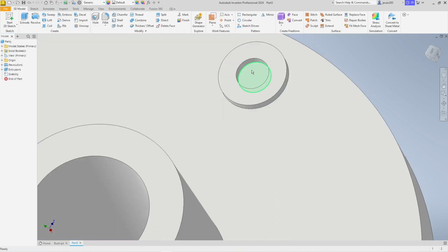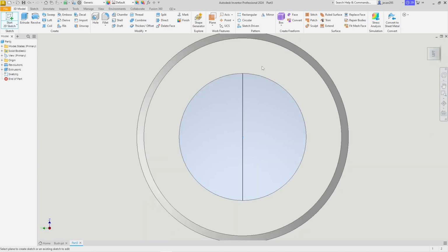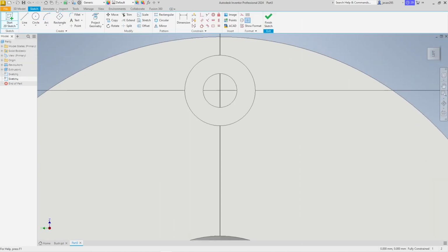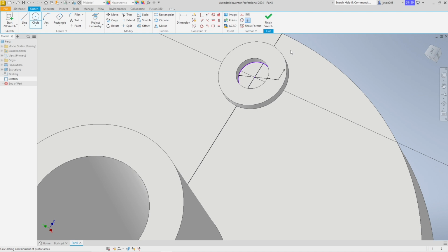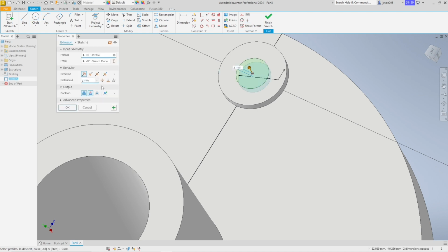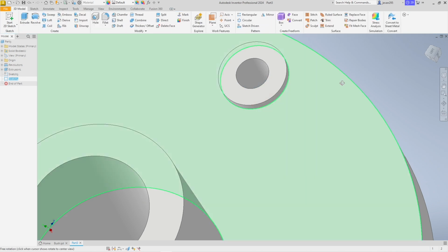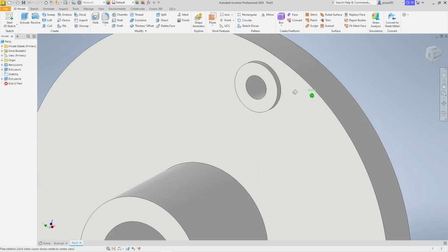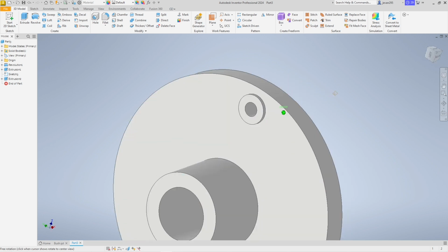Perfect. We then need to create a new shape, a new sketch, for example, on this drawing here. So we're going to go new sketch, zoom so we can actually see it, because it's going to be a pain like that. Go there, and make it the 12 millimeters that it originally was. You can either snap or just press 12. We then want to extrude this down and cut all the way through, and then press OK. We now have a hole. Perfect.